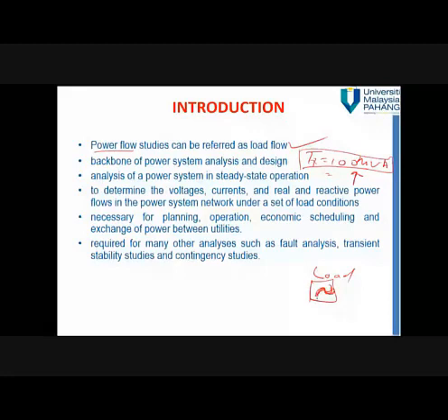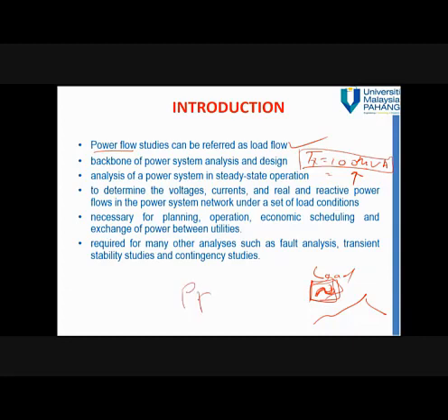Sometimes load is increasing, sometimes load is dropping. Usually load is increasing during the working hours, and then load will decrease towards the night and early morning. That's why we study steady state. That means we take one value of load at a specific load, and then we study the power flow at that specific load size. We study the steady state.